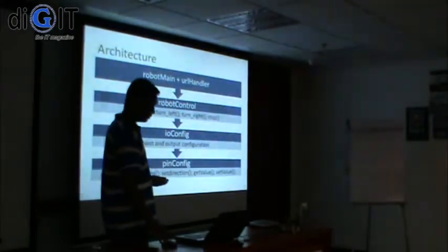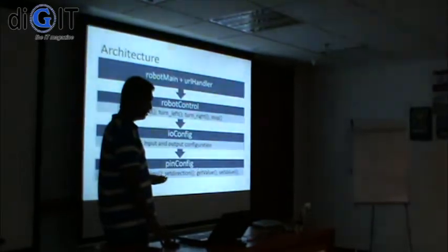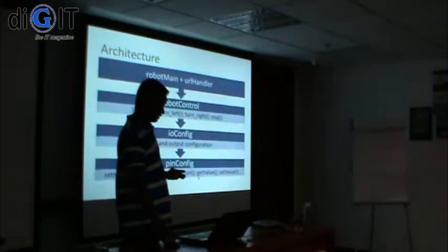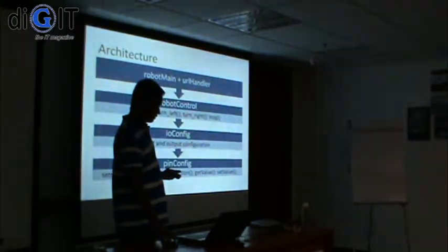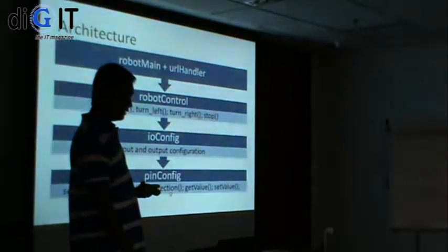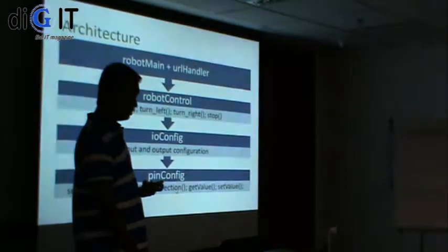Architecture of the software board is like this. First I configure the pins, the general purpose input output pins, using those functions. First you have to export pins, then you have to set the direction of pins, whether it is an input or it is an output.